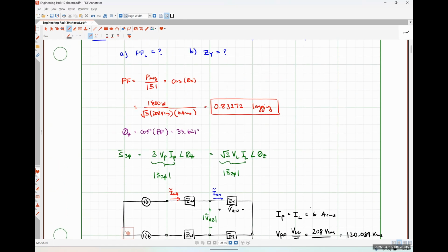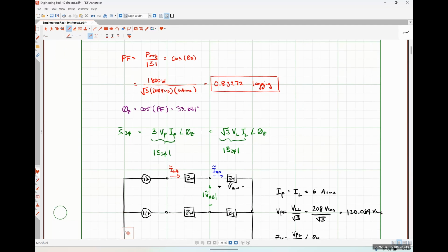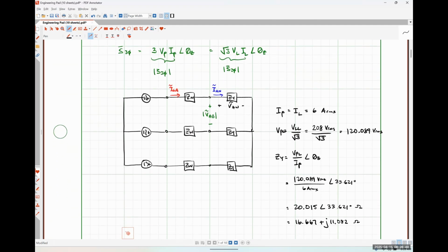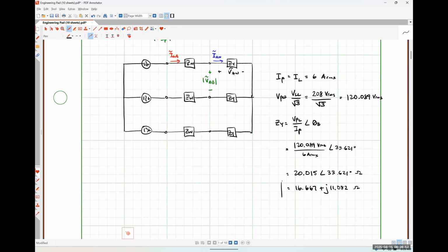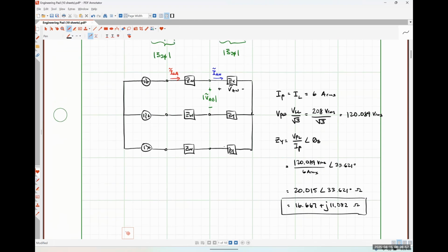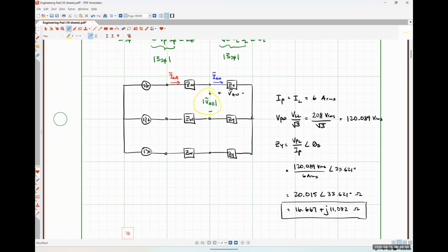So we solve for our power factor using our average power and our apparent power, which we haven't used that relationship to do very often, but it is the fundamental definition by which power factor is defined. Then we figured out what our impedance was, and the hard part is remembering that the ratio of line voltage to line current is not going to be the magnitude of the impedance, because that line voltage on that Y-connected load isn't the voltage drop across the impedance itself, right?